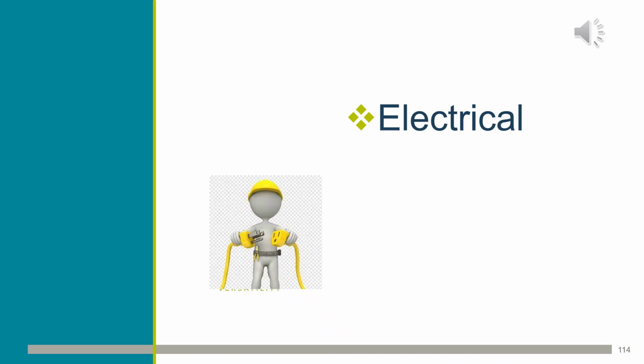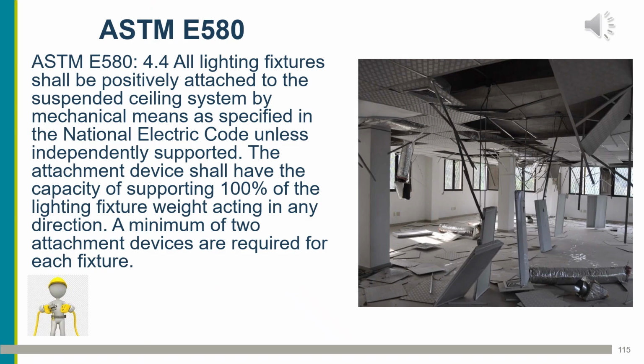So now let's discuss the above ceiling or ceiling grid type inspections and how it relates to the electrical systems that we're going to see. You'll see on the photograph to the right a very extreme example of the 2x4 troffer lights just kind of laying at the floor. The only thing that's holding them up is the electrical connections, probably MC cable.